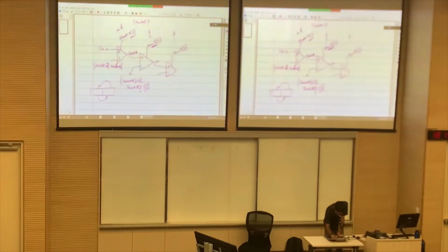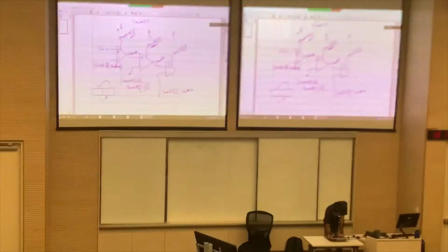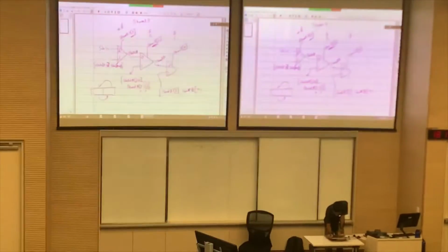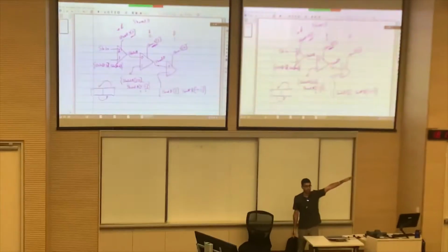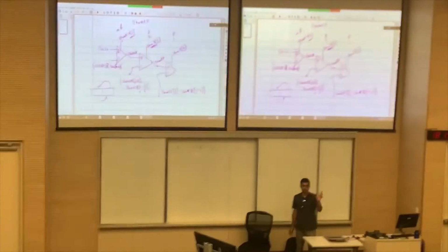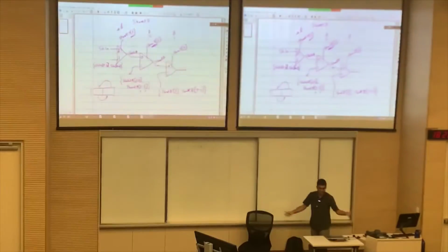Here let me just label it as SH out B. So this is the unshifted version, and this is SH out B, so we just have a rearranged version here. Bit 0 here, SH out B bits 7 down to 1, so that your least significant bit now becomes the most significant bit, and every other bit is shifted right by one position. Okay, so that gives you a rotate right circuitry.